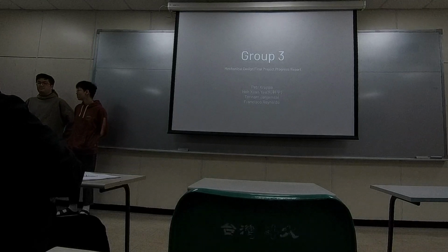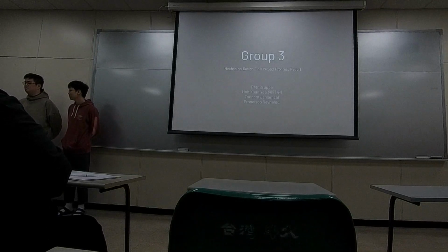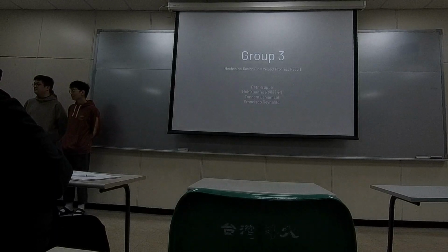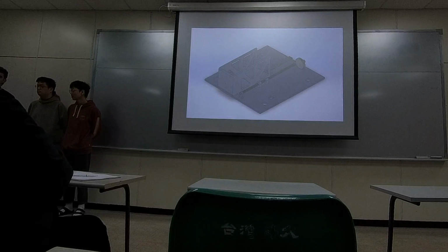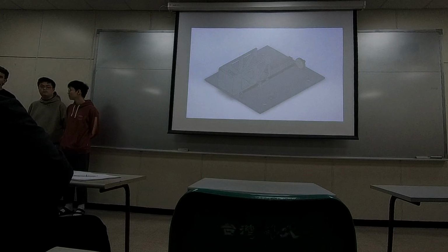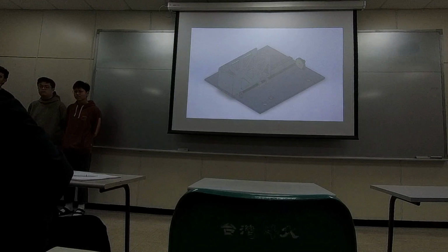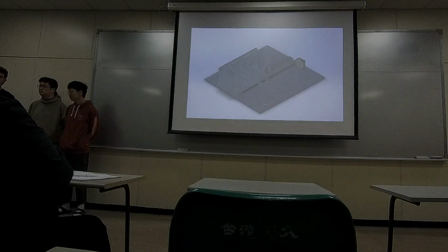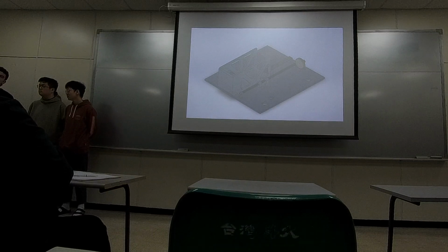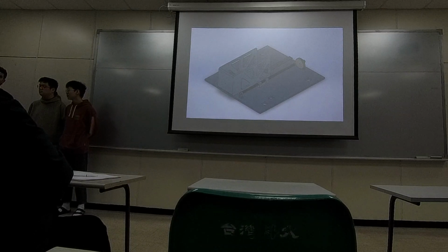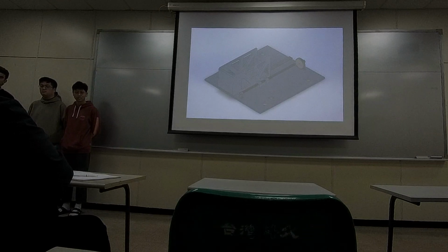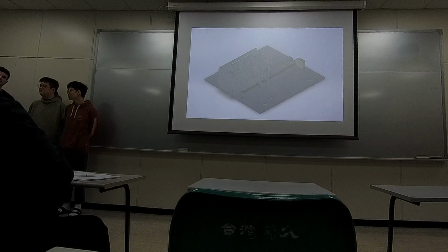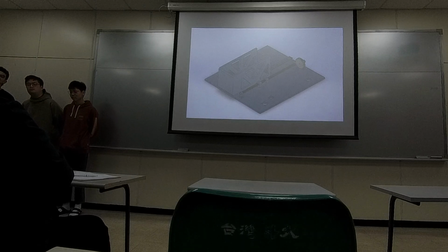Okay, so in the proposal, we said that we are going to change the gripper, but eventually we decided that just the gripper is not enough, and it's not really the thing that we're looking for because it's not a big change. So I talked to the professor, and he said that they wanted to redesign the robot in order for it to work with heavier rolls. The previous model was designed for 10 kg rolls, and this one we tried to design for 50 kg.